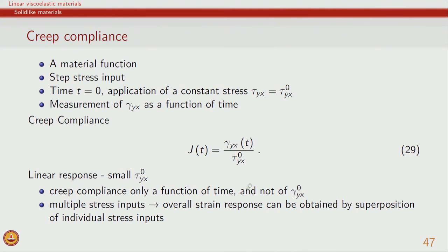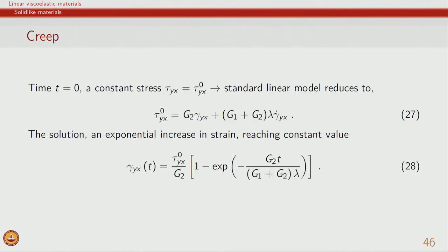The creep compliance will only be a function of time and it will not depend on the level of strain. Because a linear response is observed, we can apply multiple stress inputs and the overall strain response can be calculated by superposition of the individual responses. Strain increases and then becomes constant for a standard linear solid model.